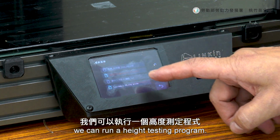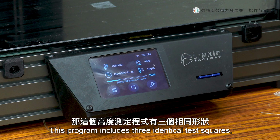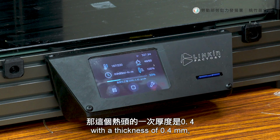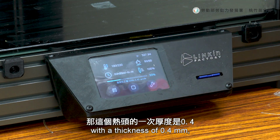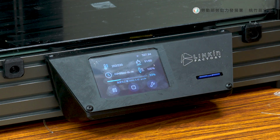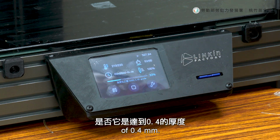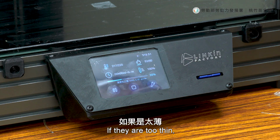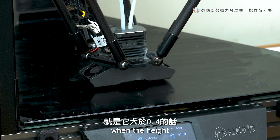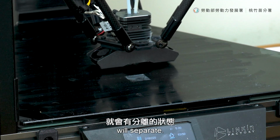Before we conduct the printing model, we can run a height testing program. This program includes 3 identical test squares measuring 1.5 by 1.5 centimeter with a thickness of 0.4 millimeter, which should match the nozzle layer height. We can observe the 3 pieces to see if they match the thickness of 0.4 millimeter. If they are too thin, the extra material will accumulate. If they are too high, then the height is over 0.1 millimeter. Then the layers will separate.